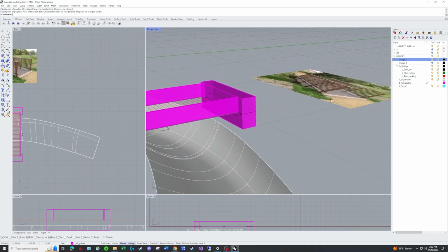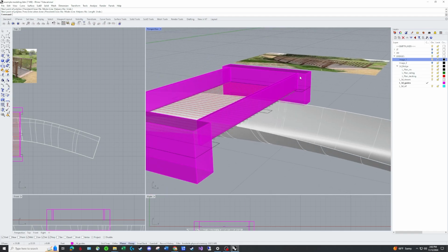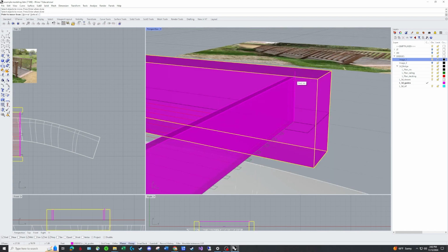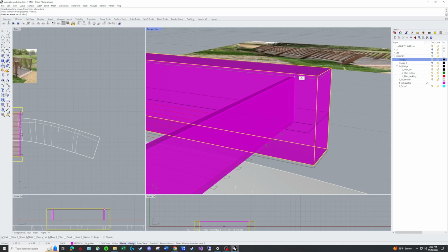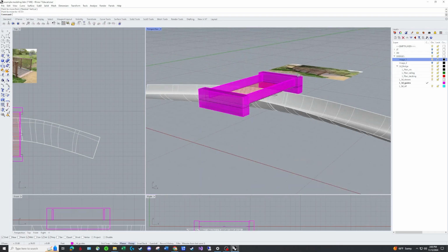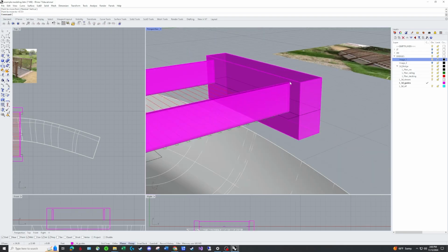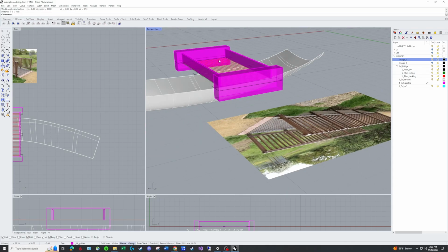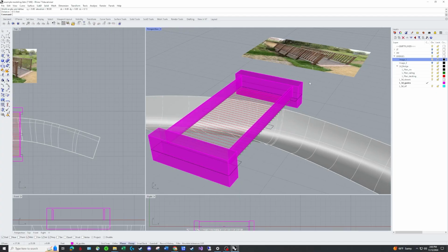Now in the image, as you would think, the decking and the curb and the path are all flush, so I could just extend this a little bit more, but I'm just going to be a little bit lazy with this and not worry about the underground part so much. But I definitely want those to meet, so I went ahead and raised it up, and that should be 1.5 inches, or 0.13 feet if you're doing decimal math in your head.